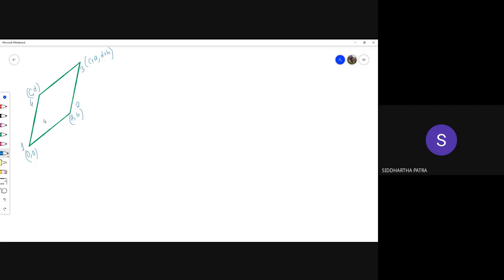When you are getting the expression for the Jacobian, also try to simplify it. Okay, so some terms might cancel out. Now don't focus on the diagram I've just drawn. I'll talk about it in a minute, but just try to get the general expression for the Jacobian for a general quadrilateral element, an arbitrary quadrilateral element, which in physical space could be anything. And what I've drawn in black ink is a trapezoid. The actual quadrilateral might as well not be a trapezoid.